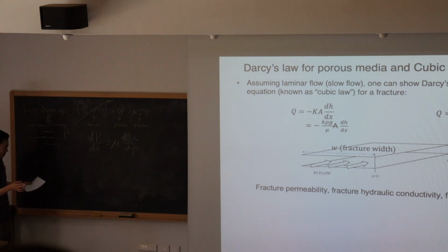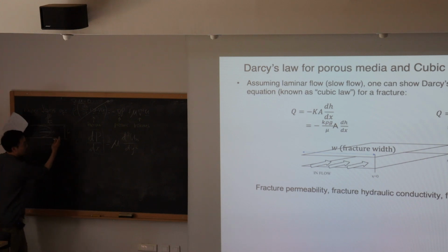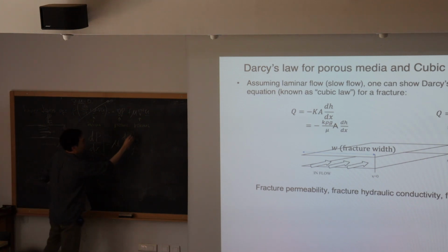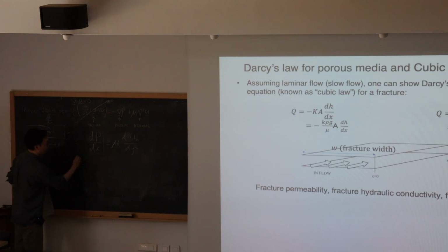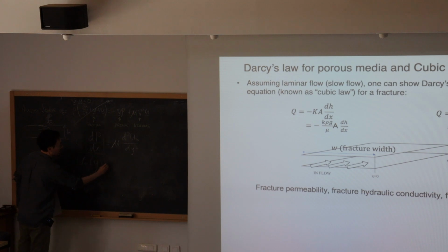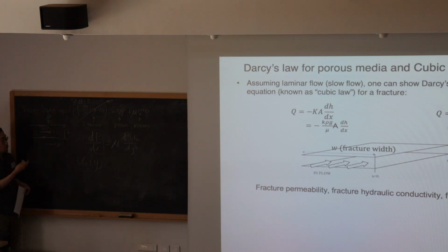And that's it. You have to simply integrate this equation twice because this is given, okay? So you can treat it as constant because this is a boundary condition. And what you are after is ux, right? You just need to integrate this twice to express ux as a function of y, right? And there will be two unknowns because it's a second order differential equation, right? That means we need two boundary conditions. So what boundary condition do we have?